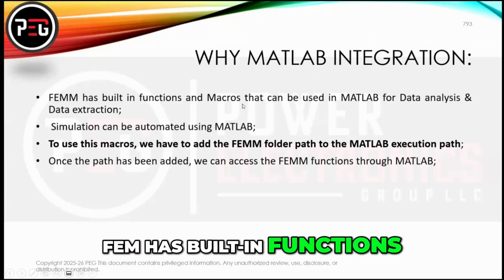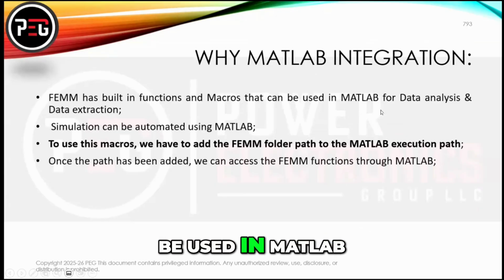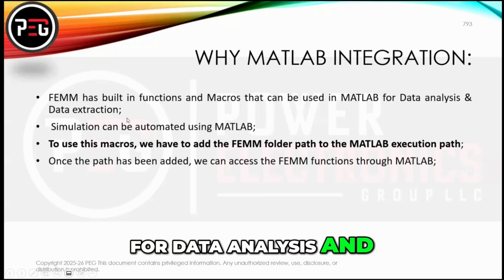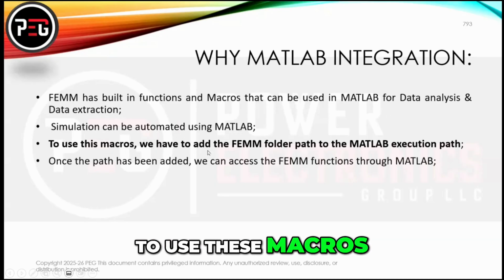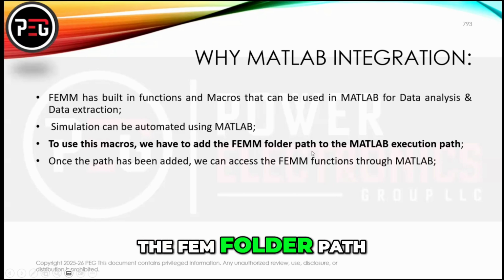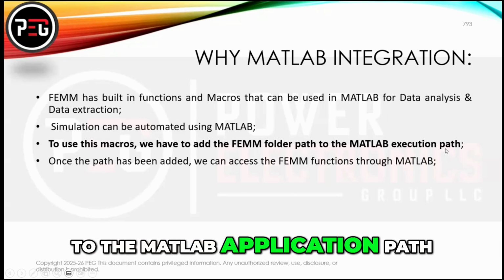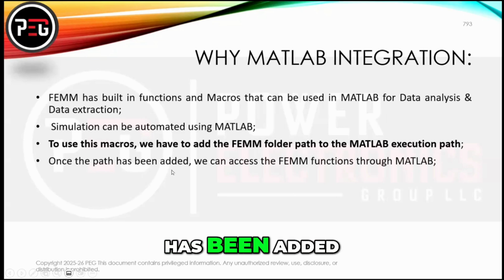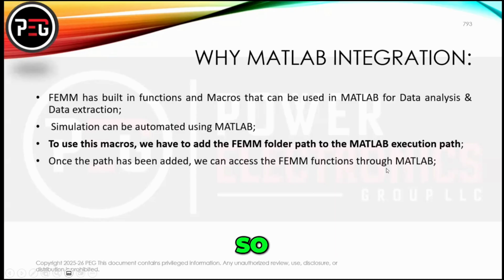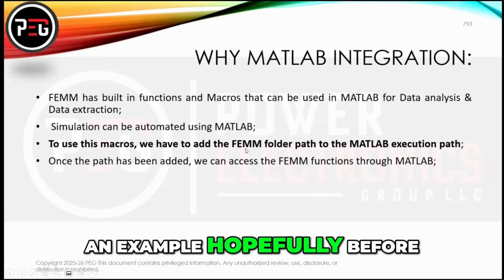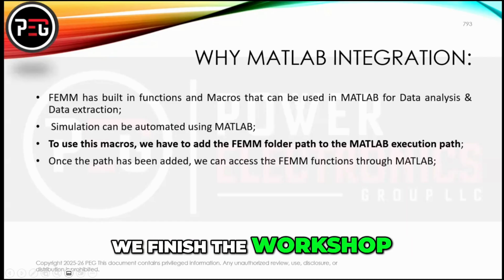And then you can use MATLAB to run the whole thing. FEMM has built-in functions and macros that can be used in MATLAB for data analysis and data extraction. Simulation can be automated using MATLAB. To use these macros, we have to add the FEMM folder path to the MATLAB execution path. And once the path has been added, you can access the FEMM functions in MATLAB. Okay, and I'll show you an example, hopefully, before we finish the workshop so you can get an idea.